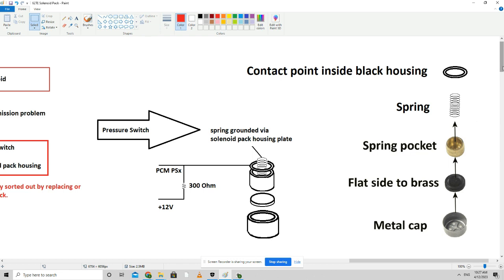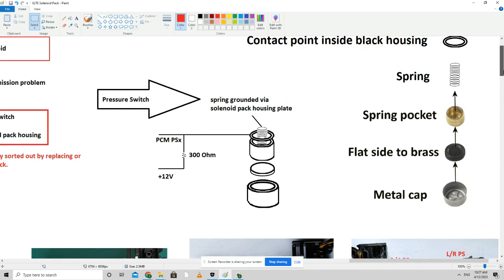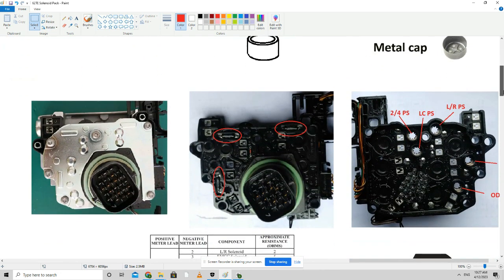And this contamination usually comes from the torque converter clutch, which usually wears off after 100,000 miles or sometimes before that. And that's exactly why regular maintenance of the transmission is required. You have to change the fluid regularly because these particular transmissions produce a bit of muck in there. The torque converter clutch wears off quickly. So let's have a better look at it.